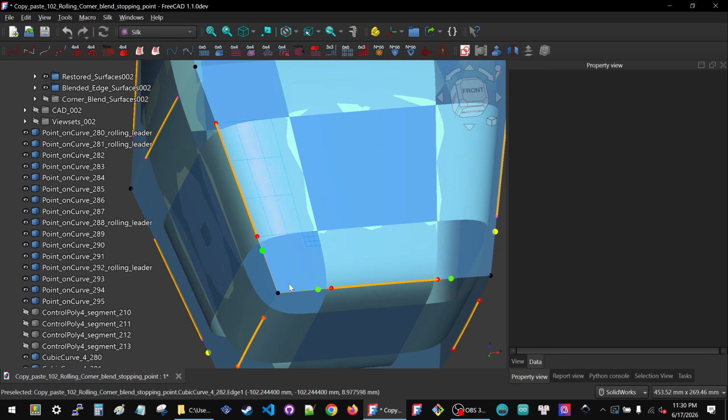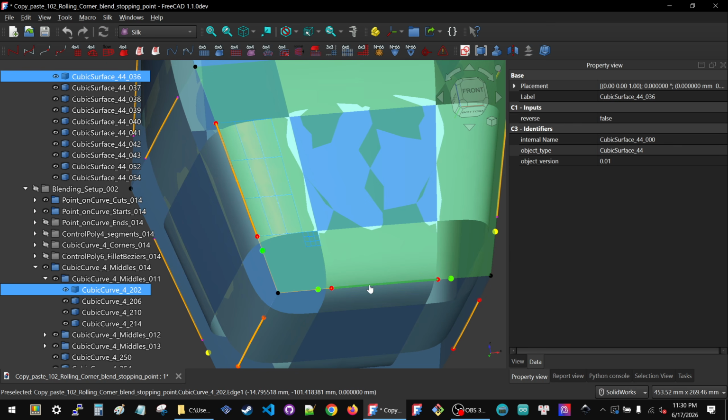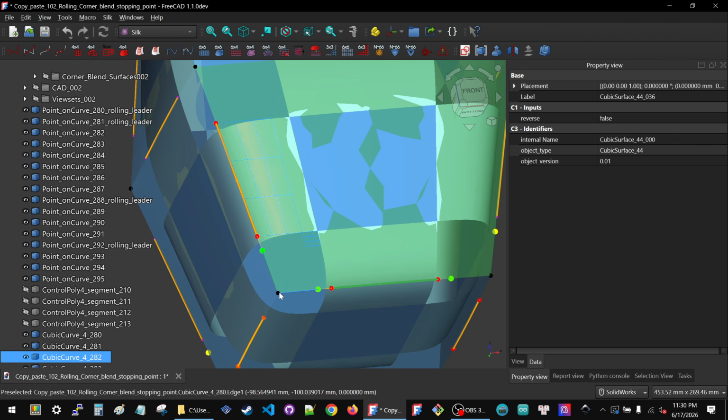We're just going to do it for this corner, but that means we need to adapt this blend and we need to adapt this blend. So for this blend right here, it comes from this surface. It goes this far along the edge itself. And how far back should it go? It should go back this far. Instead of going all the way to a red point, the new one will be only this far back. Surface, middle, and new inset. Create the segment.